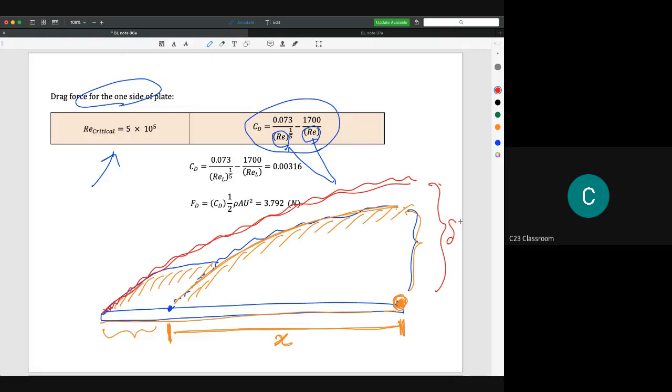So we use this equation. This is the equation that we will use. The idea is, if you see, 0.073 is actually the CD for the total turbulent boundary layer, and we need to subtract a certain amount. This amount is the unnecessary part, to reduce the total value a little bit, because the laminar part only gives a small, not so high, value of resistance. I hope you could read this in the previous notes.